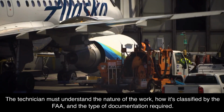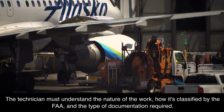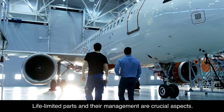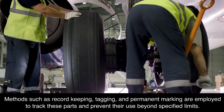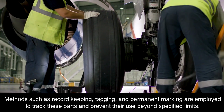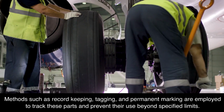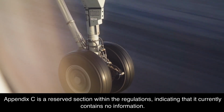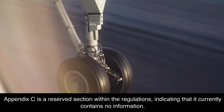The technician must understand the nature of the work, how it's classified by the FAA, and the type of documentation required. Life-limited parts and their management are crucial aspects. Methods such as record-keeping, tagging, and permanent marking are employed to track these parts and prevent their use beyond specified limits. Appendix C is a reserved section within the regulations, indicating that it currently contains no information.